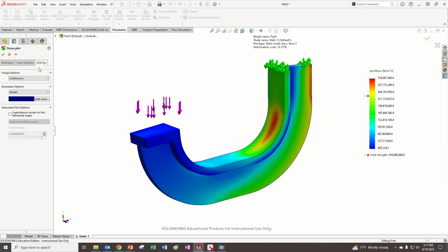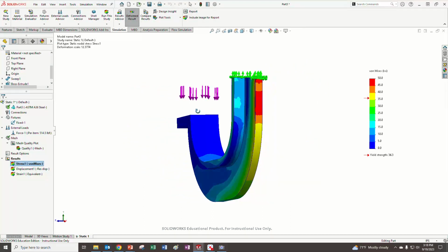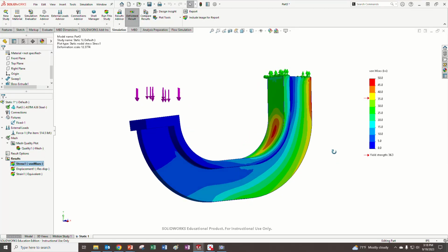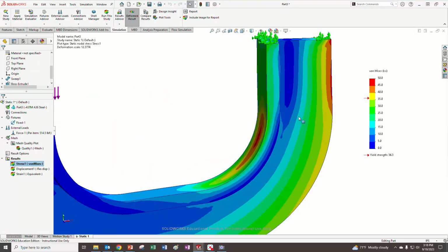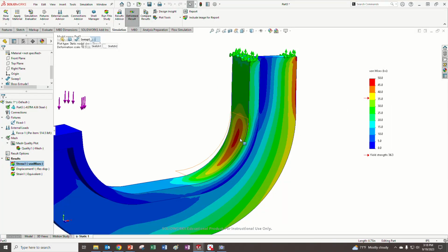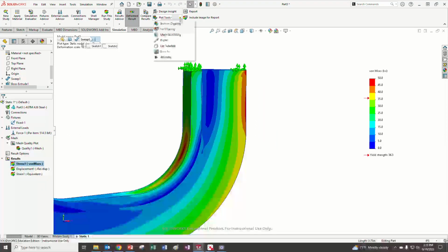And then the last setting I always change from continuous to discrete, so you can kind of see where the demarcations are in there. Oh, interesting! Right here is where the stresses are, right? Where the highest stresses are located right there. But I think my calculations were for right here at this location. So that's one of the reasons why we have higher, like we see in red. Let's take a look and see if my results were correct.